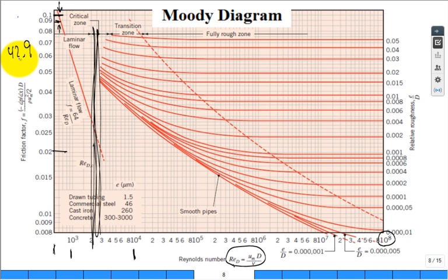Somebody else, oh no, my friction factor is 10 to the minus 8th. Really? Okay. Let's explore that a little bit, because it should be roughly between 0.01 and 0.1. Now, yeah, you can extrapolate a little bit beyond, but most of it is where the action is happening. Got it? All right, so what's this red line doing over here?